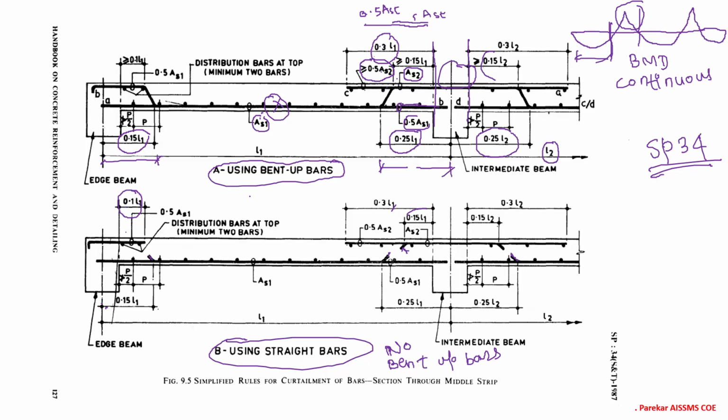Second question you may be given: show the clauses of T-beam. Now we have clauses of T-beam. We have two. One, when a beam will act as a T-beam: if my main reinforcement of slab is perpendicular to the span, it will act as a T-beam. Or if it is parallel to the span of beam, then it will act as a rectangular beam. Then to act as a T-beam, we have to provide transverse reinforcement as 60% of main. So likewise, you have questions in this one.